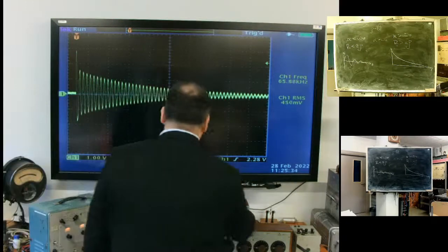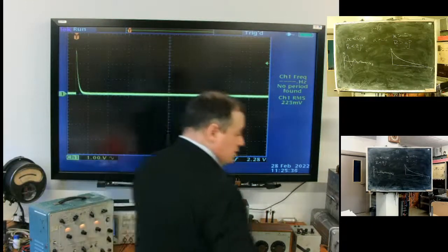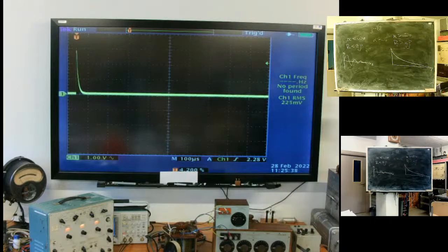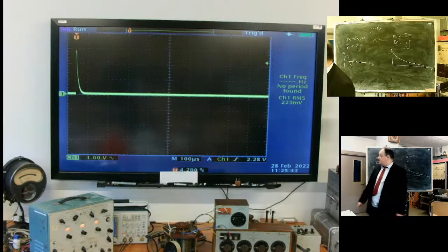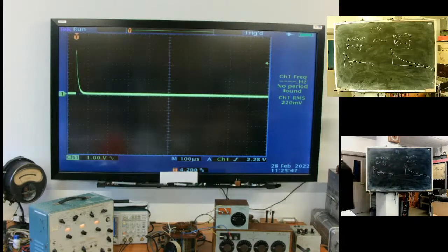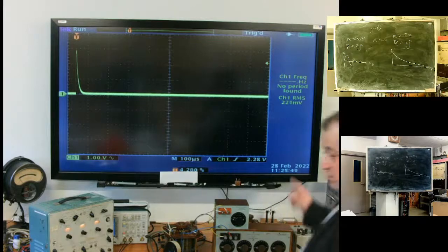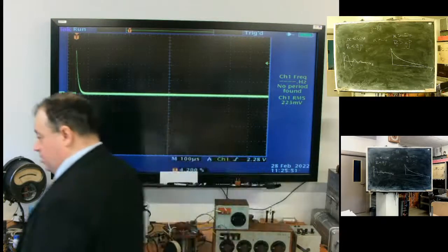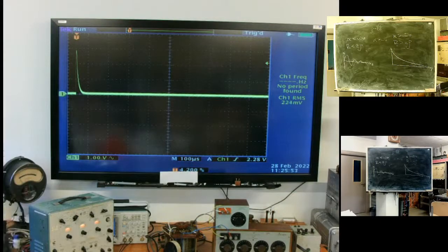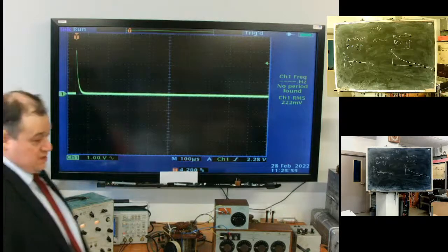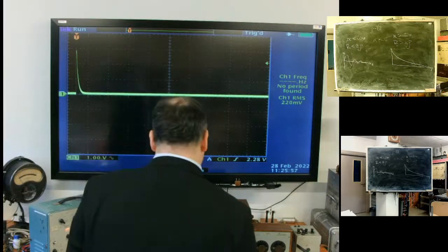If you add a so-called snubber, a special network reducing the quality of oscillation, you will have an exponential commutation process. It is much more preferable because it causes a much lower load on the semiconductor structure.